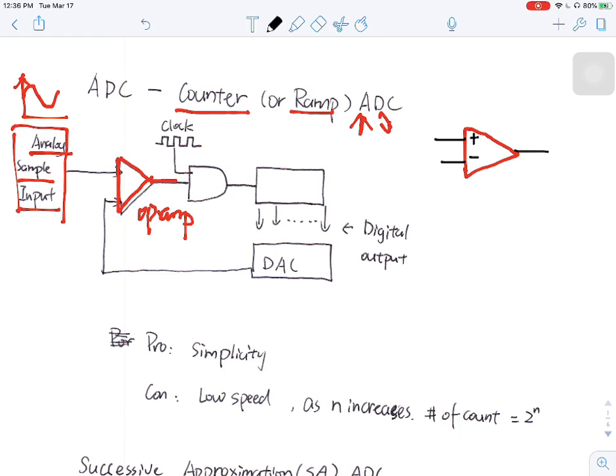In order to have a comparator, you need to connect the inverting side, the negative side, to your reference voltage, and you need to connect this positive side to the voltage input, and that's it. There's no feedback, and on output, this is V out. Of course, for an op-amp, you need to have power supplies, plus VCC and negative power supply, negative VCC.